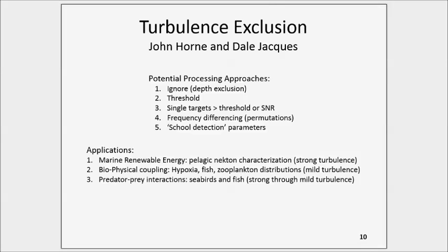You could potentially stretch out noise depending on what your signal is that you're interested in, because anything that's not signal is noise, but typically that will bite into what you would consider data, and we've got to make that trade-off reasonable. If you're interested in single targets or target tracks, then you potentially could look at thresholding, but depending on your signal-to-noise ratio, that may or may not work for you.